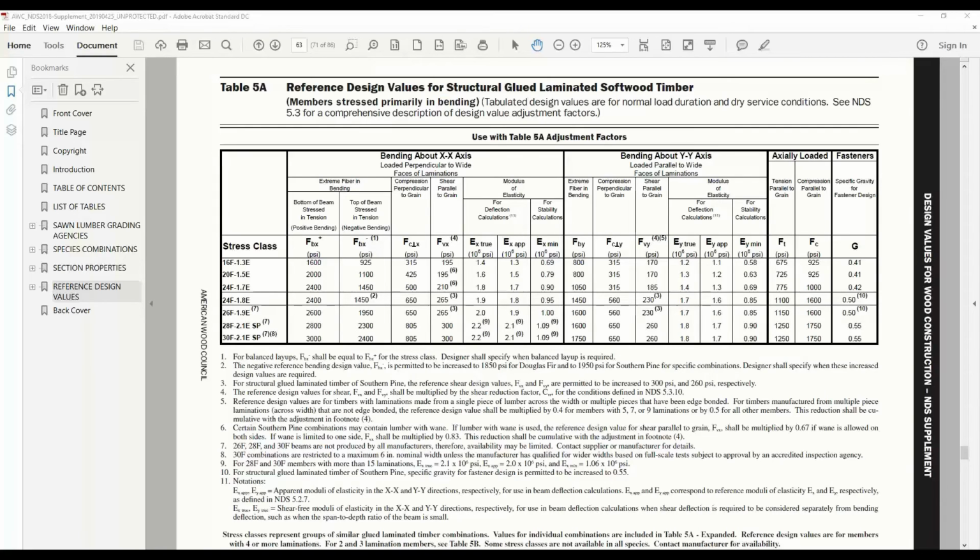I don't think you really need to get it under a microscope. The thing to look for, because a lot of times these checks do happen near a lamination in the beam, and that's where some confusion happens, is whether you are seeing any wood tear in there. You have to get in there and look at the wood tear. If it looks really clean, you're seeing clean glue lines and you don't see wood tear, those are the things you need to look for in the field. I don't think you need a microscope, just a magnifying glass and a good light. Measure the length of the check, measure the depth, and get a thin ruler in there to make your assessment.